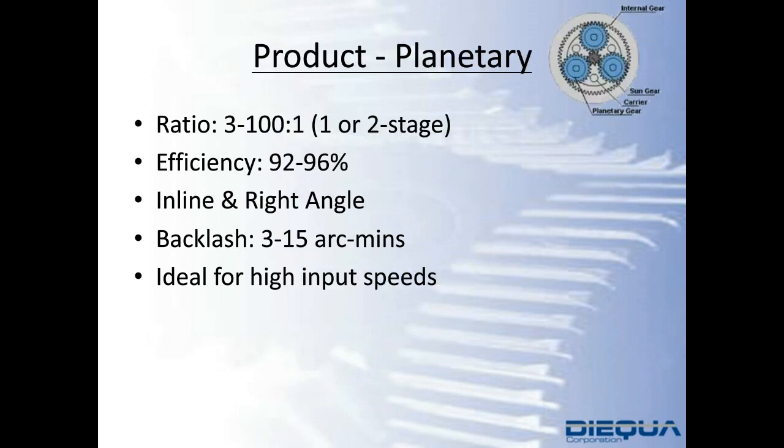Okay, the next reducer that allows you to have a rotary output flange is a planetary type. This planetary gearbox gives you an inline concentric solution. It gives you, in a single stage, a ratio between 3:1 up to 10:1. And here I am illustrating 100:1 as the high end, but this is simply because you could do a 2-stage. On occasion, you have seen 3-stage planetary units.